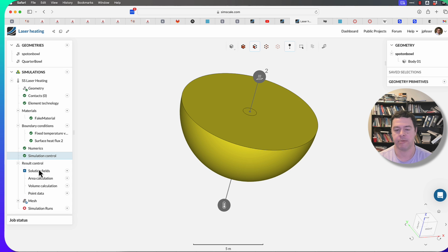So how much heat flux, in this case, leaves through the bottom boundary should be equal to the amount of heat carried in by the laser. If I did everything correctly, I designed it to be a 1 watt laser. So I'd like to check that 1 watt is actually what was delivered. This is part of my verification process, so you can ask for numbers like that.